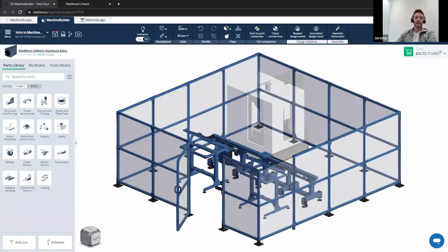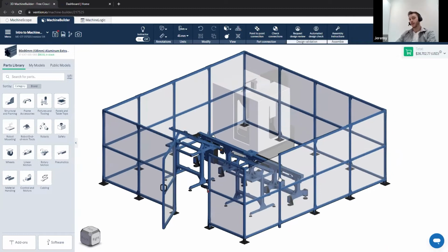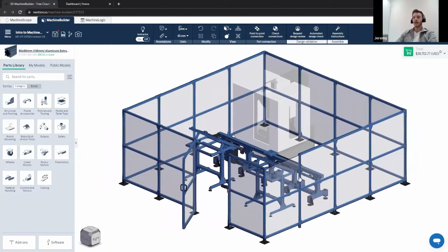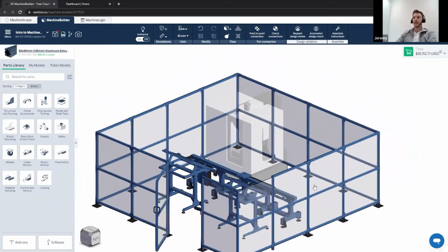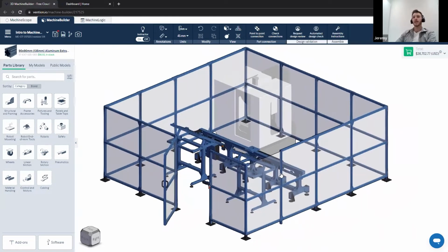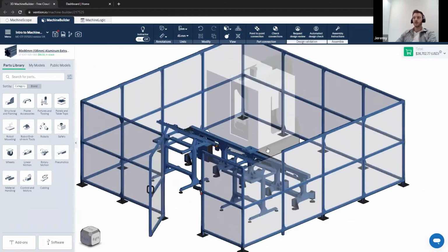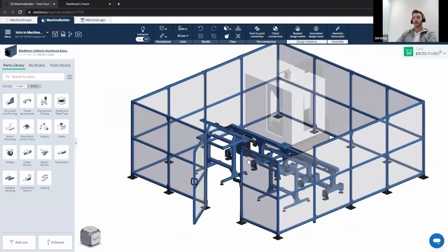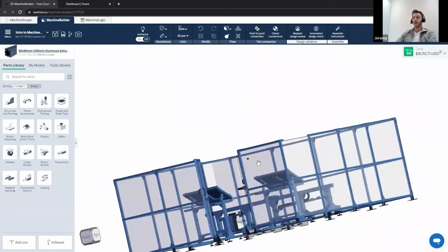So from there, I'll do a little bit of the navigation. So you saw me moving the design around a little bit, but again, I'll go over this. So first, you can pan the design around. So if you right click, do note that I am using Vention's controls, so it might be a little bit different if you're using SolidWorks or AutoCAD, but for the Vention ones, you can right click to pan the design around. What this does is simply moves the design space or the camera in the design space, but doesn't actually move the design itself. Otherwise, you can zoom in and zoom out using the scroll wheel and also rotate around. If you click on the scroll wheel itself, it will rotate around the point that you click.